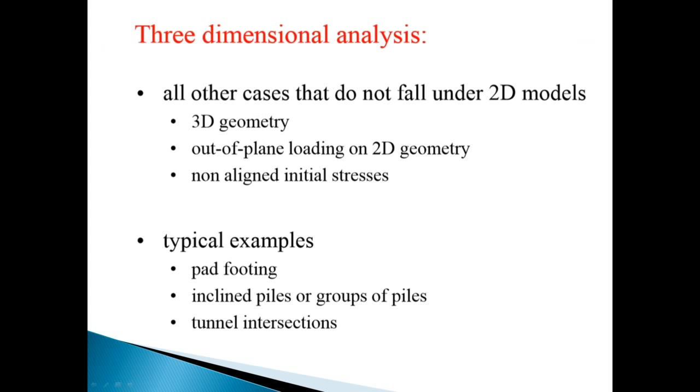Okay, 3-dimension analysis. Once again, this requires the greatest amount of time investment. This requires the most amount of skill to do successfully, but it can be used for all types of projects. And it's not limited to projects that are symmetric, and flow can go in the z direction. Once again, this is a higher level of analysis which will go on in some more advanced classes. But just to give you an idea of the power, the capabilities that lie within 3D analysis, I've included this here. And these are just a couple of examples. Pad footings, tunnel intersections definitely require 3D analysis, and also inclined piles or groups of piles would require analysis in 3D.